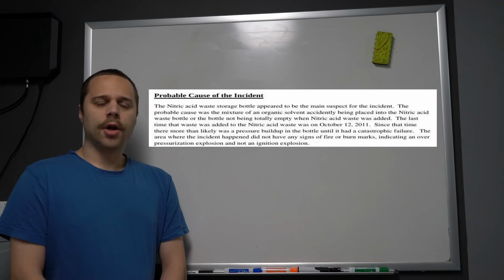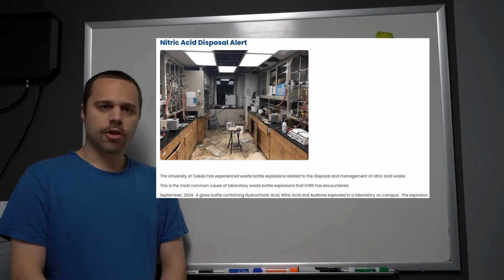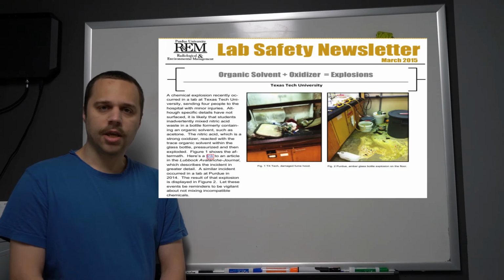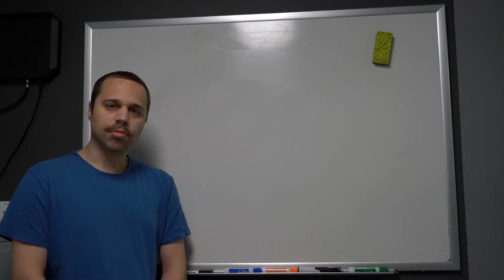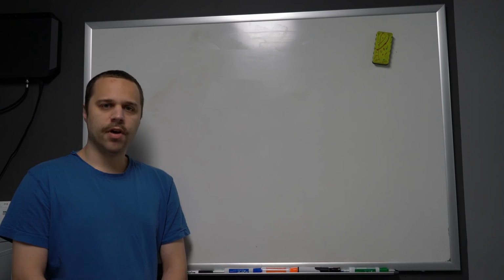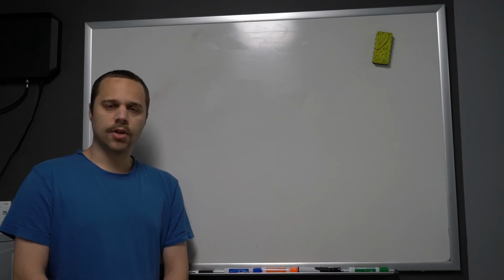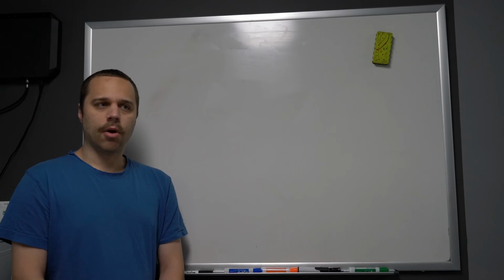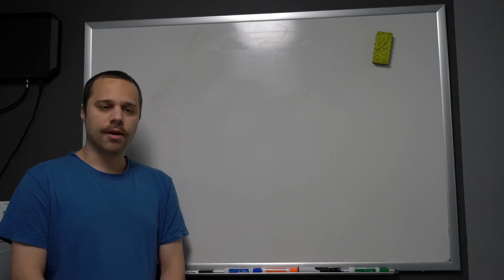So first of all, I don't want to underestimate the risks. There have been a significant number of incidents. If you look up almost any university EH&S website, they've probably got an accident investigation of someone who mixed up the solvent waste and the acid waste containers in a fume hood, poured solvent into acid or acid into solvent, and an hour later the fume hood blows up. So this is a real thing. It does happen. There is significant damage and injuries that result.